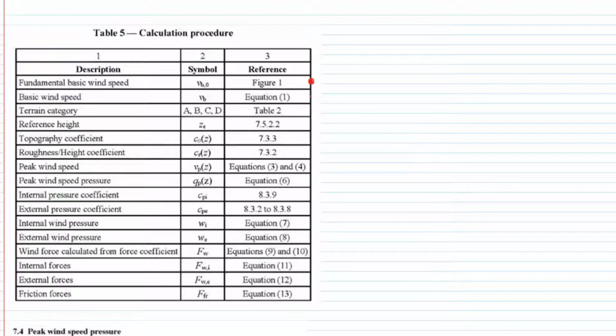And then we adjust the wind speed to account for certain parameters. Then we need to know, my building, my farmhouse, my multi-story skyscraper, is surrounded by buildings or vegetation or mountains or whatever it is. How does that affect it? And then once I've got my terrain category, what is the reference height to know what height to get the wind pressures at? Consider topography.